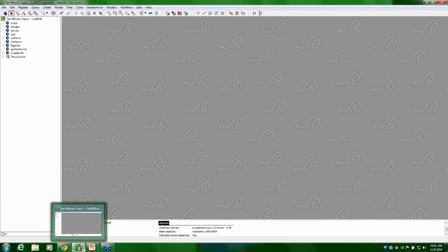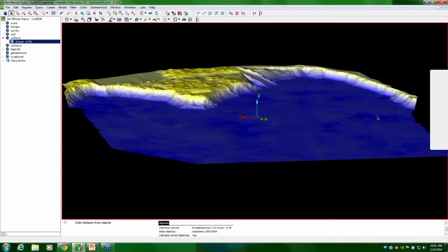So like Burton was saying, we're going to be running through some site data to get a really nice visual for showing where a bench is and isn't conforming to design. So today we're just working with a flat bench for an open pit mine. And we just want to know where the big extreme cut and fills are before we achieve design elevation. So we're going to go ahead and start with a surface at this point. Obviously we've already registered the scan data and created a topo surface.